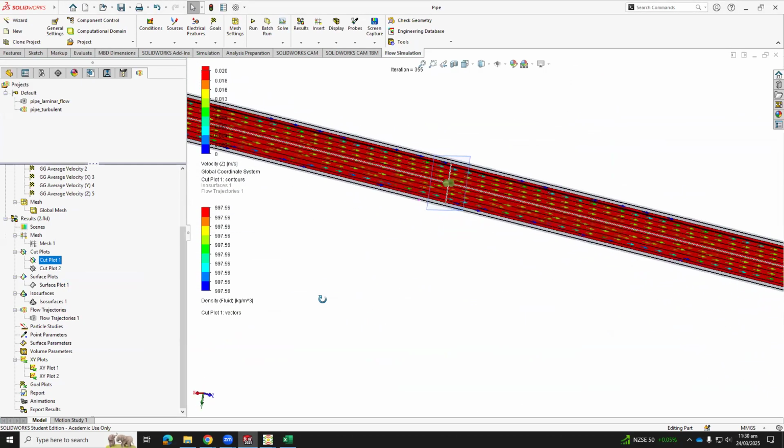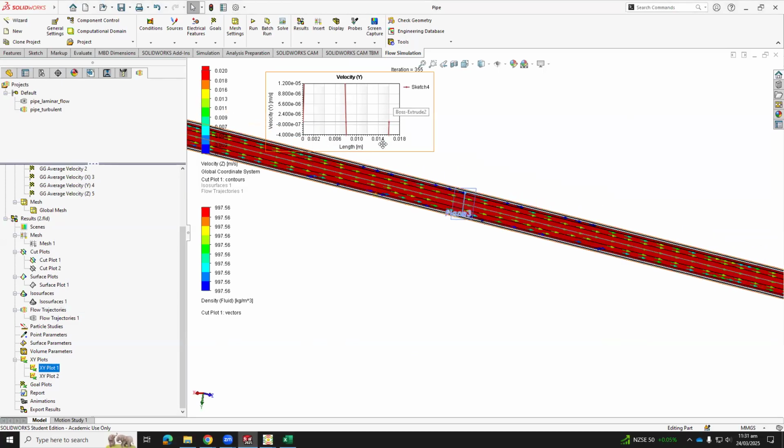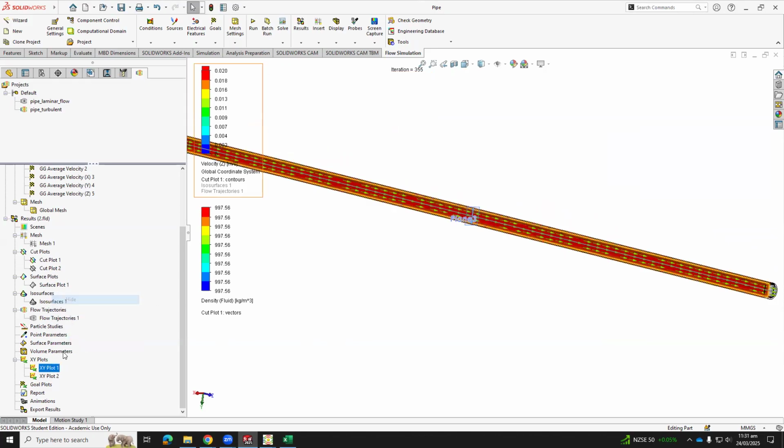We show you the results we produced previously. However, when you do an XY plot, I don't recommend you show the old one again. You go and create a new XY plot, because if you change some of the values, it may show you the range very funny. I'll show you an example. See, they don't show everything. The scale has become higher and it sketches everything on the previous scale. So I will not rely on that. I would just insert a new XY plot.